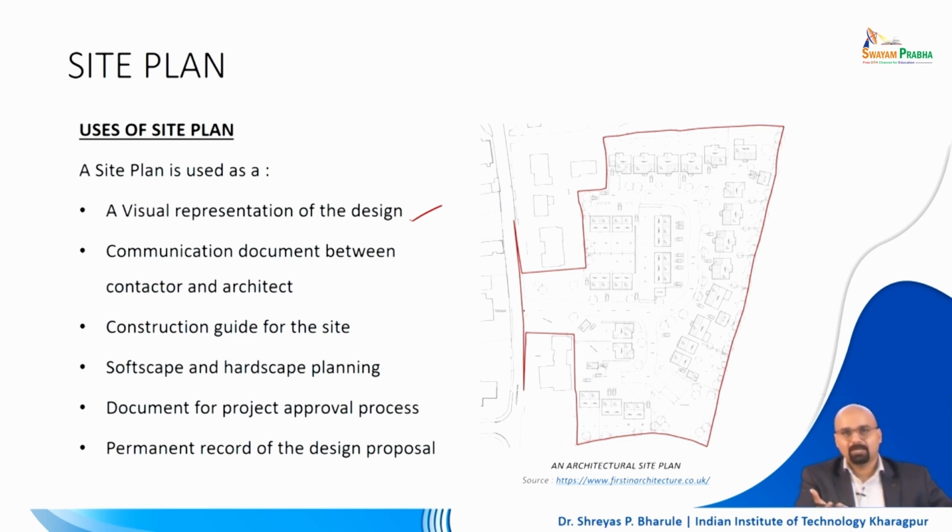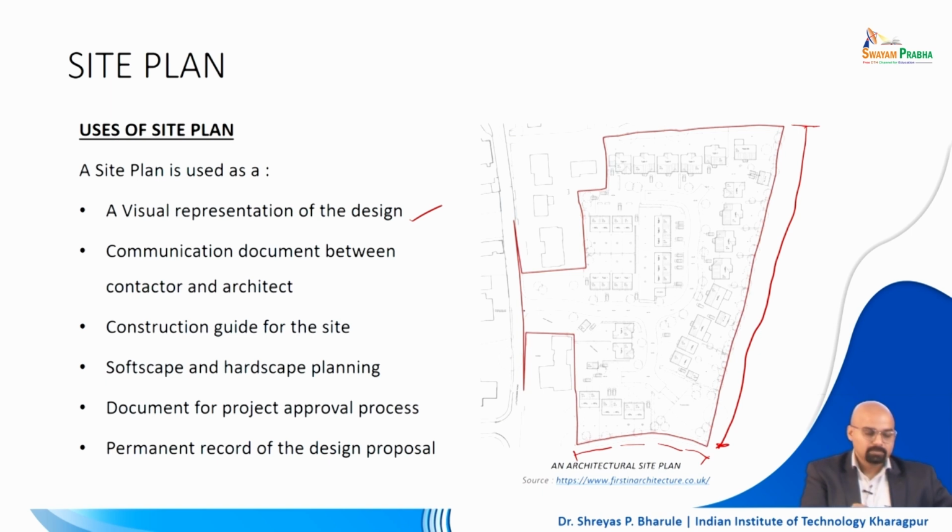However, the second drawing which is shown in the master plan is without the rendering, you have an actual site plan which shows the dimensions of the site, which shows the expanse of the site, how large the site is. Say for example, in this case it is from here to here and then the dimensions are somewhat like this, right. So, you have a very different irregular kind of shape in this case. It is kind of a semi trapezoid.